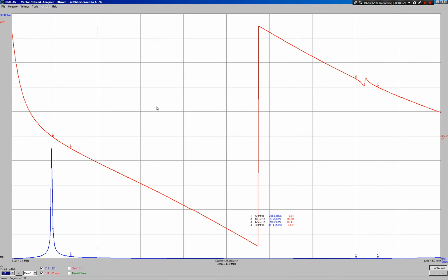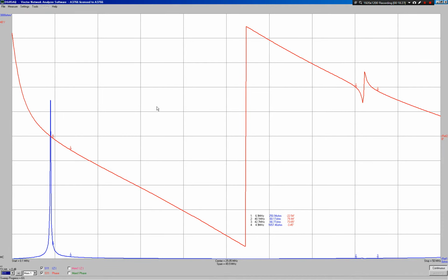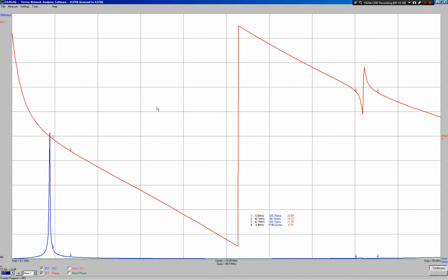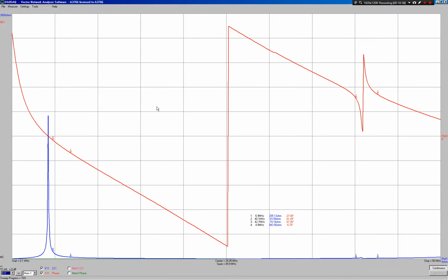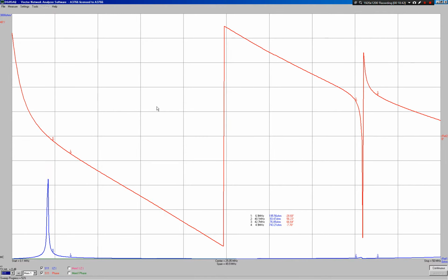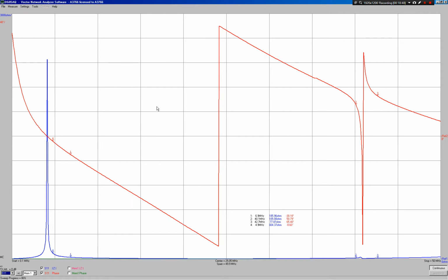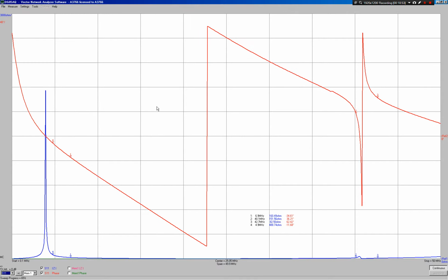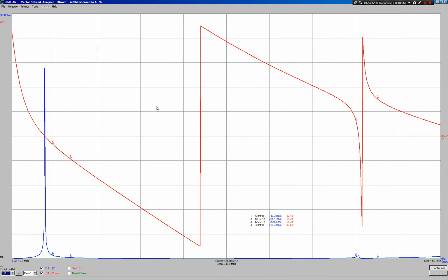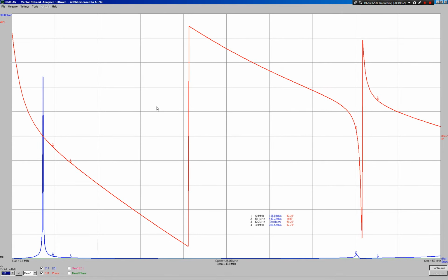We're going to keep going down. You see the change is rapid now. As I load that capacitance on, that phase is working its way very quickly downwards in frequency. The parallel point is also moving down. You see also that higher harmonic opening up again as it's no longer consumed in interaction with the lower harmonic. Keep moving downwards, and you'll start to see how this